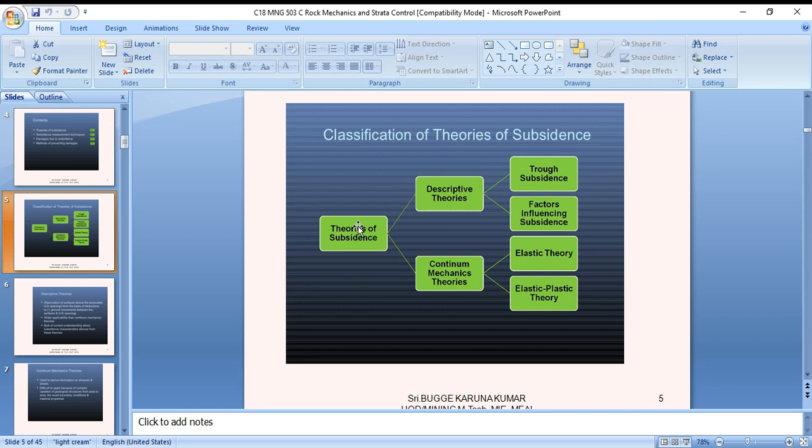Caving is a form of subsurface subsidence in this treatment. However, the term is restricted to a process where either or both the rate of failure or the area over which the failure occurs is at least partially controlled by the mining method, as for example in a block caving operation, as contrasted to subsurface subsidence, which to a much greater degree is an uncontrolled process, whereas subsurface subsidence is primarily a result of the gravitational force acting on the rock surrounding or overlying an opening.